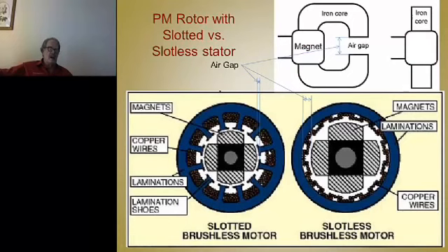Those conductors are wrapped around a soft iron pole piece. They're wrapped around a piece that looks like this. And the air gap, these two teeth here represent the pole faces of this air gap. So where are the forces on this wire? I guess they're there, and mathematically they're still correct. But what these conductors do is they magnetize this tooth here, and let's call this a north pole.